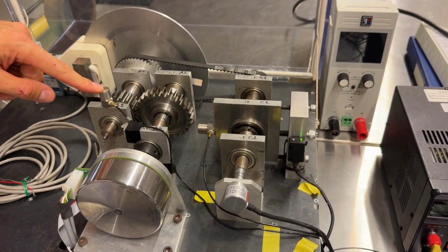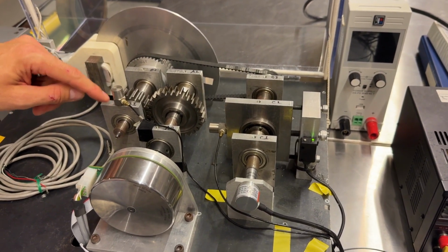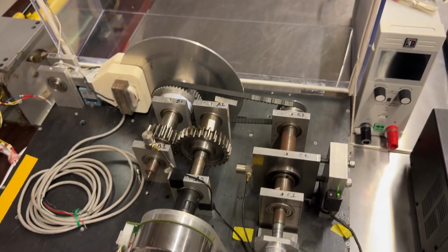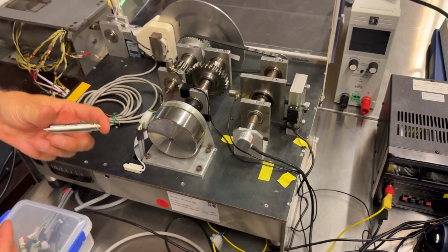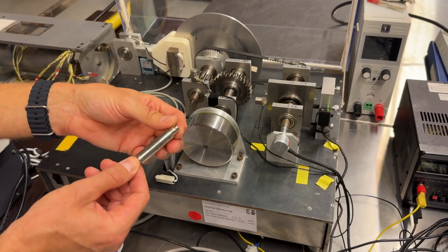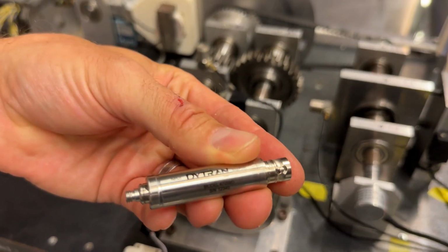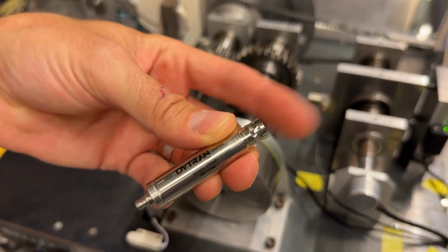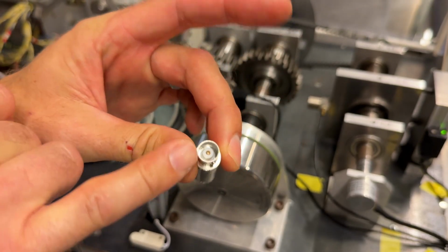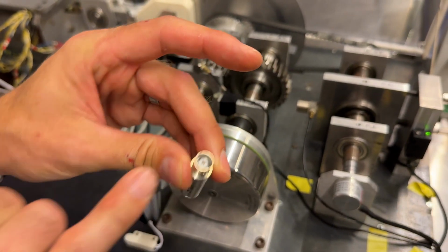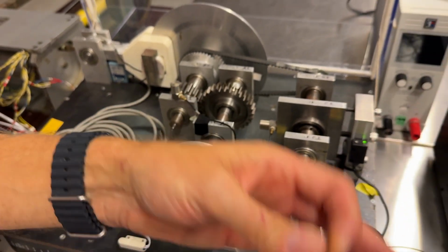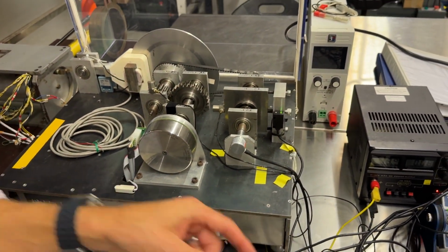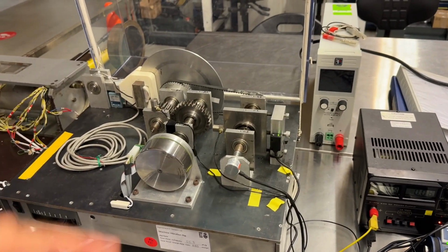We have another accelerometer mounted to this shaft housing over here, and these are both charge mode accelerometers, and the signal conditioning is provided by our inline charge converters that are IEPE powered, via this end to the acquisition system, and this end's connected to the accelerometer. We have two of those in line with the cabling that's connected to the acquisition system.